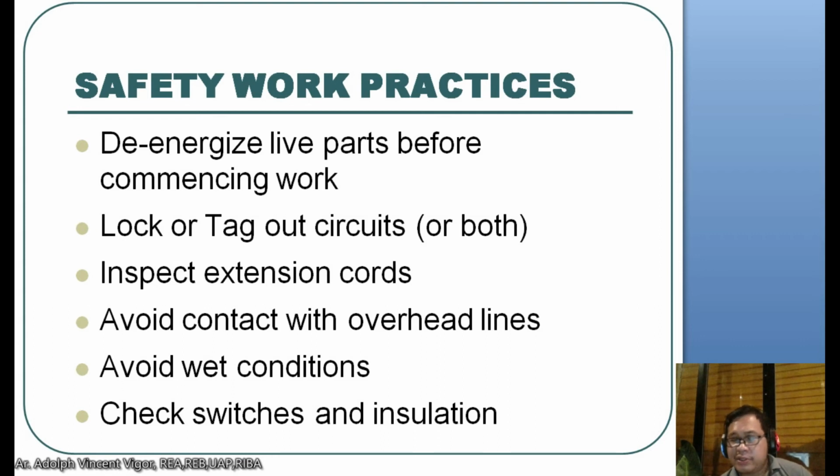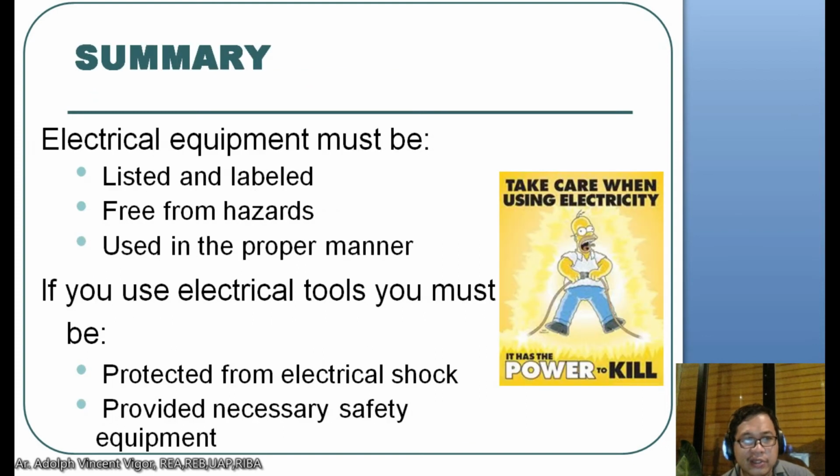Okay? Also de-energize live parts before commencing work. Lock or tag out circuits. Inspect extension cords, avoid contact with overhead lines, avoid wet conditions, and check switches and insulation.